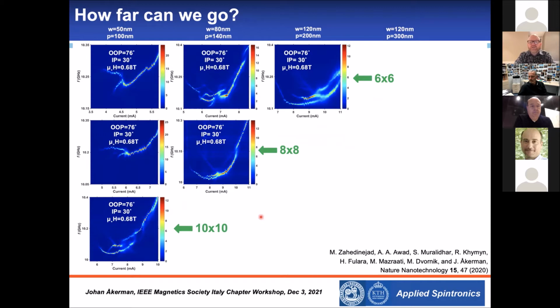The more oscillators you add to the array, the greater the chance that they will break up into separate, partially synchronized regions, especially since we are primarily dominated by nearest neighbor coupling. This will indeed become the result. So to get even better synchronization after this, we should still shrink the separation and strive for even closer behavior, or more similar oscillators, with less distribution in their properties.